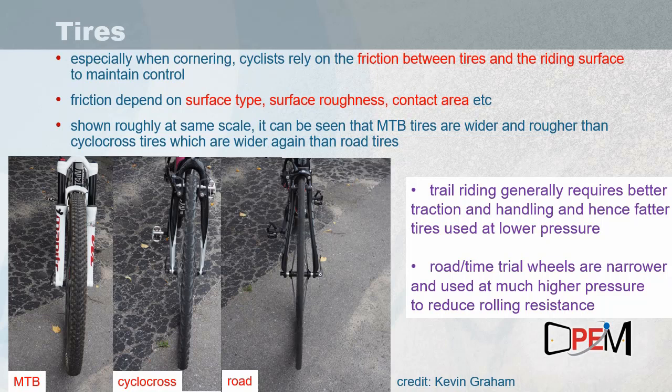In the case of cyclocross tire pressures, at least the professionals ride at very low pressures, something like 20, 18 psi or so, or to translate into SI units, it's a little over 1 bar or a little more than atmospheric pressure. There, again, you're trying to maximize the traction, especially when trying to go around the very sharp corners designed into the courses. But the courses don't have the kind of roughness or sharp obstacles that you might find on a trail course in mountain biking.